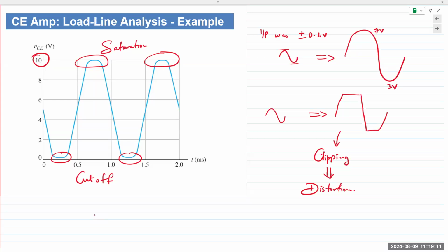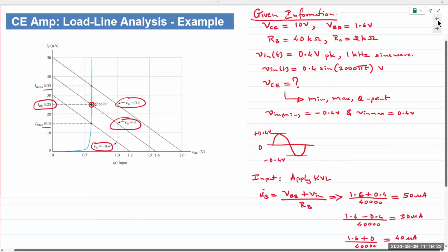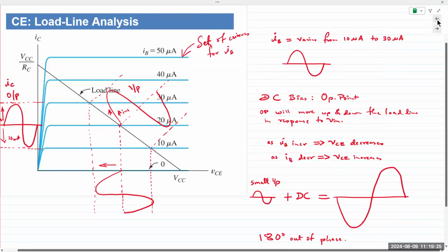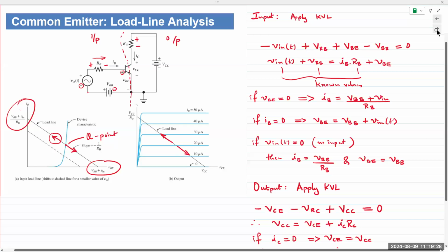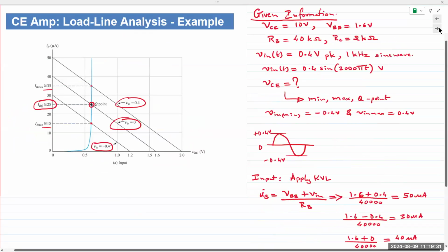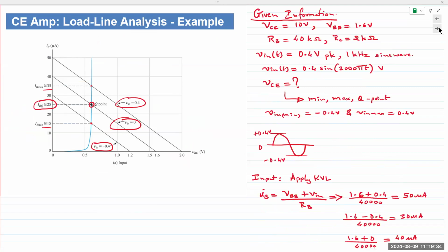Okay, so a couple of limitations. The first and the biggest one is, of course, that if the transistor changes, even for the same, let's go to this input right here, not that, this one. So here we have a value for beta, which is 100, right? That value is part of the spec sheet provided by the manufacturer. But it is impossible to fabricate two devices with exactly the same value of beta.